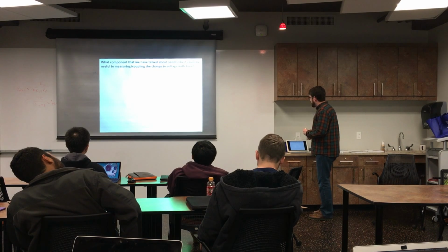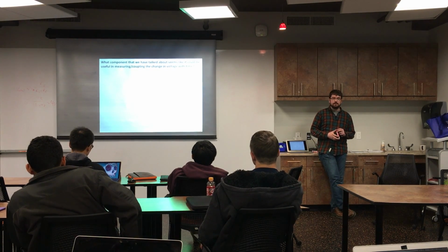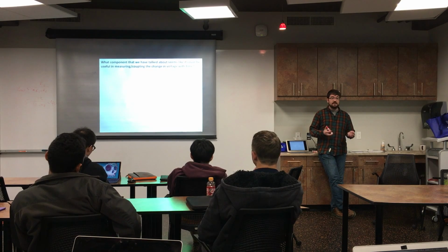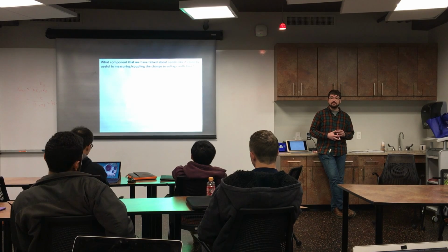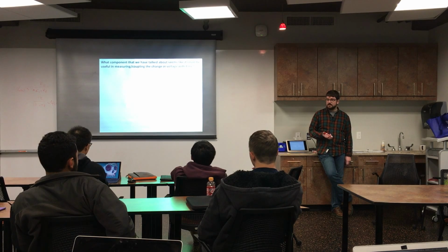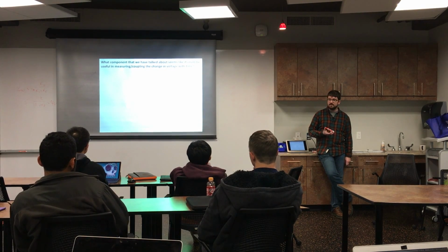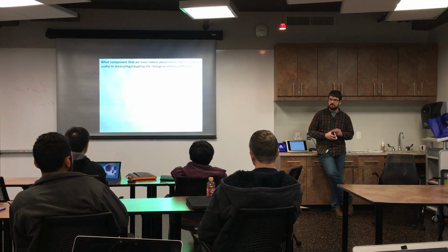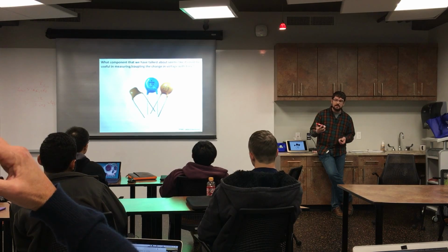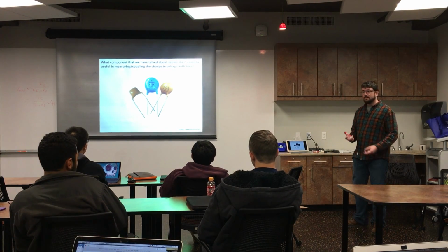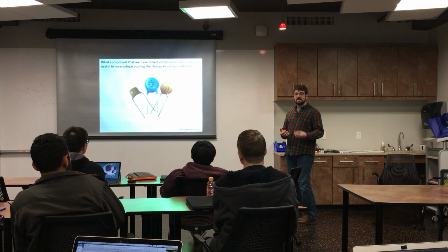Let's say we want to look at the rate of change of a voltage coming in. We want to take the derivative of a signal. Let's say that you have a displacement transducer hooked up and you want to do some kind of control on velocity. So you want to take the derivative of that displacement signal in hardware. What components do you think we could use to do that based on what we've talked about in basic components from the basic electronic theory? So we can use capacitors as one of the building blocks for this and for the integrator, as it turns out. So capacitors, we know, pass AC signals through and they block DC.